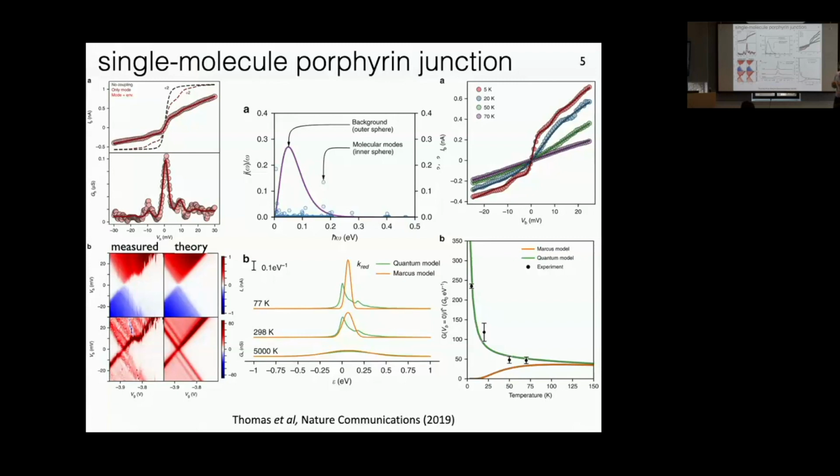This did require a relatively sophisticated master equation with some fancy stuff going in. We did make a lot of approximations. We were pleased it worked in the end. It is limited to weak molecule-lead coupling, so we're deep in the sequential tunneling regime. We don't get much throughput.